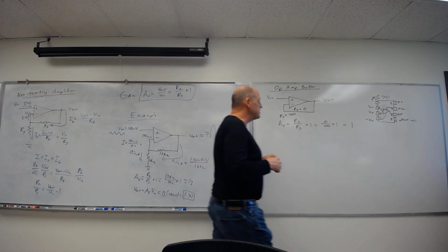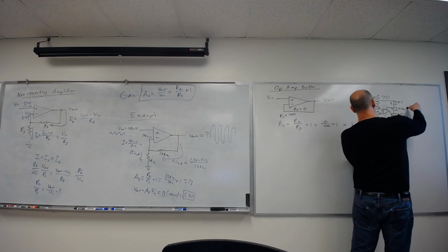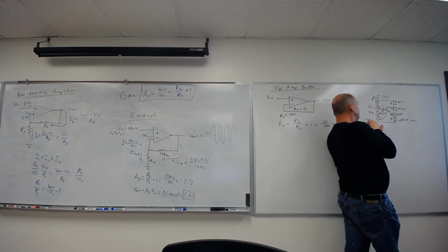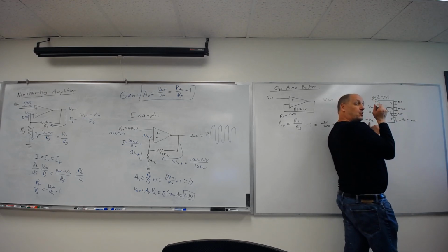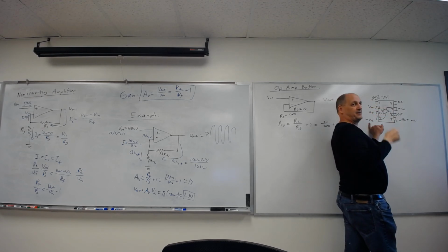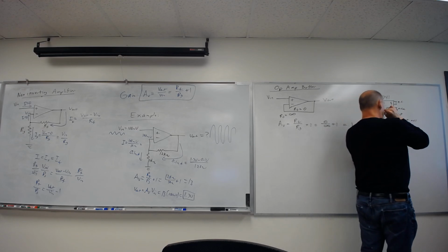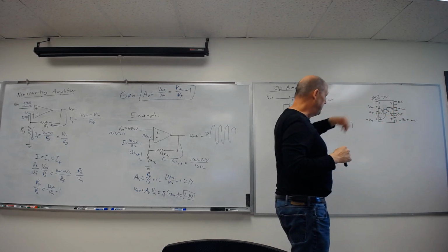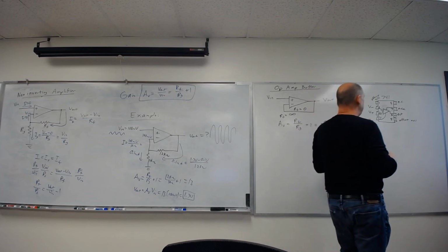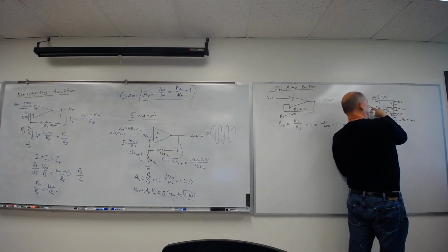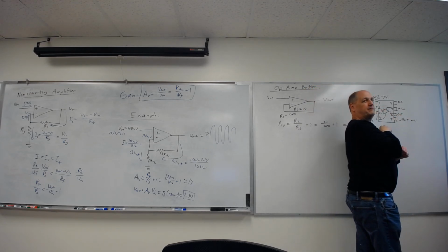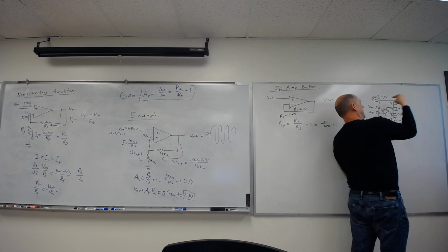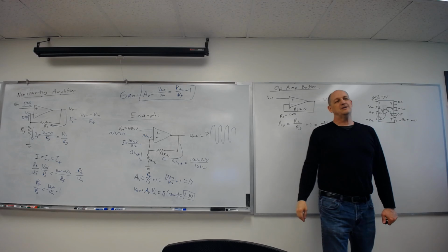So my 5 connections I'll need will be positive voltage, negative voltage. The ground's not part of the power here, but the ground will be part of the circuit because both circuits go to ground. Not negative voltage, ground. Your input will go to the other one, and your output will be just off pin 6. You're going to have a feedback resistor that goes from the negative input to the output. Don't feel ashamed to use 3-dimensional space and just plug it in on top of the transistor.